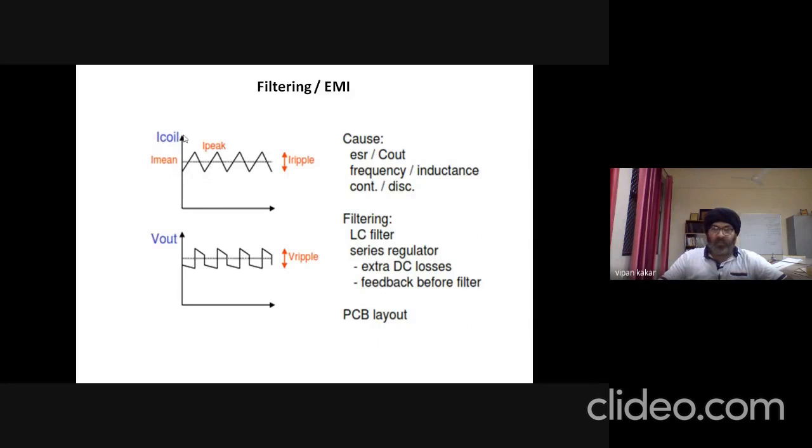Okay, so this is the inductor current. Continuous current we saw when we did the analysis in previous slides, a ramping up of the current and a ramping down of the current, and so on. This is the net capacitor current. These ramping ups and ramping downs of the currents are due to the capacitances and inductance present in the circuit, and also based on the switching frequency.